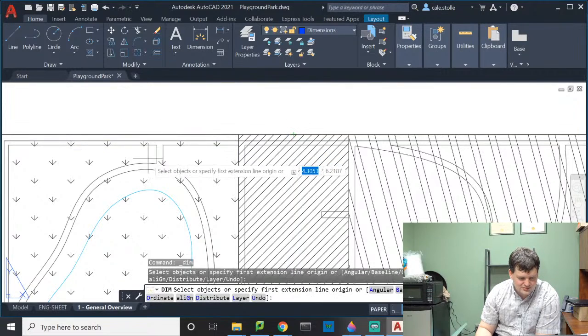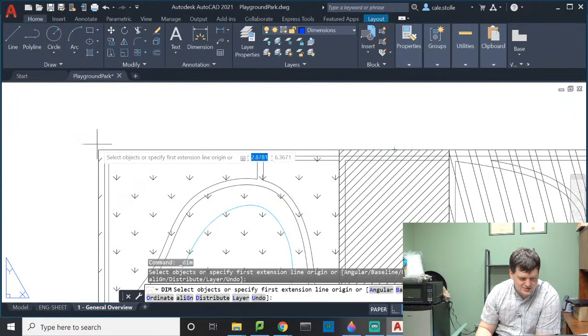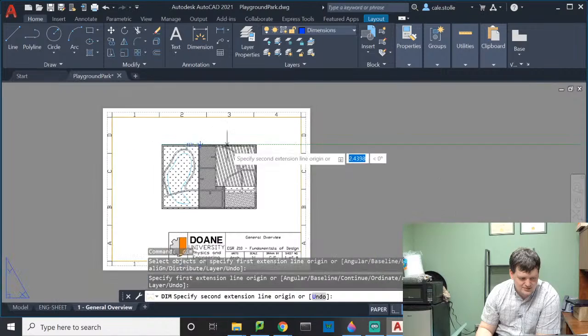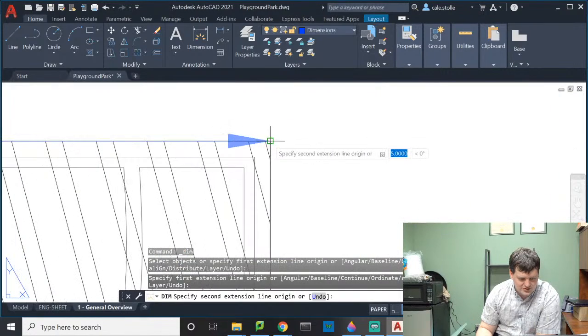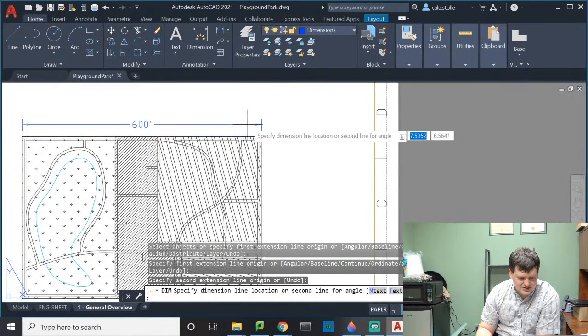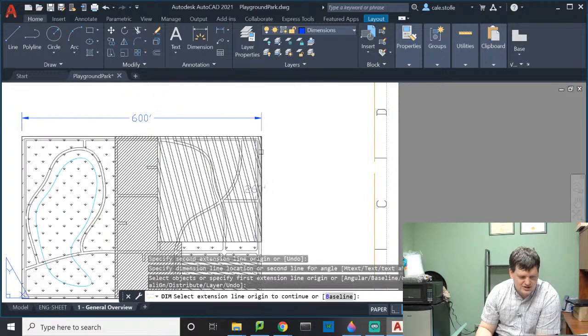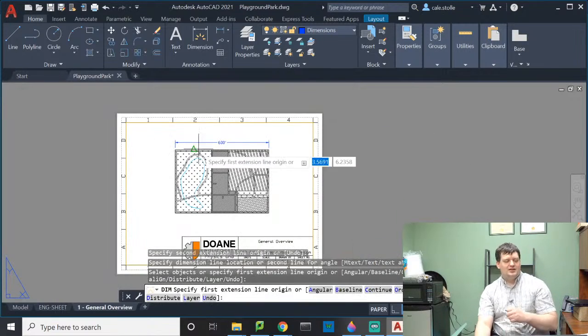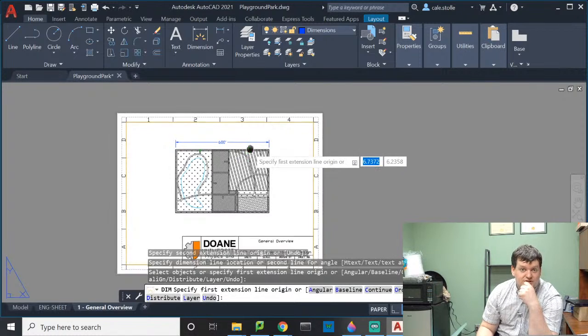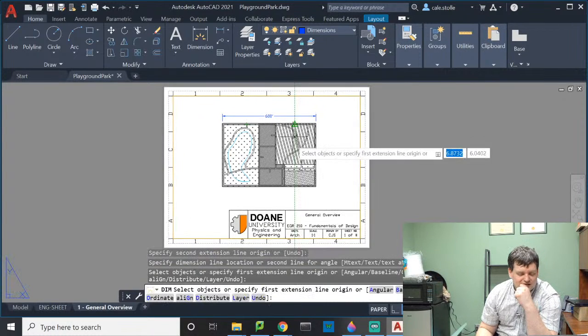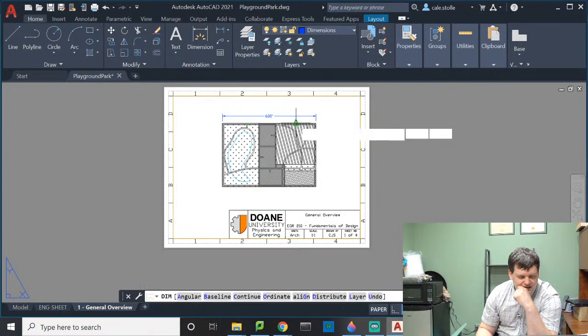I'm going to click on this corner, go over, click on this corner, and we're going to bring it up about right there. And I already set up my dimension layer. That was actually the first video that I put together, so I know exactly what this looks like.